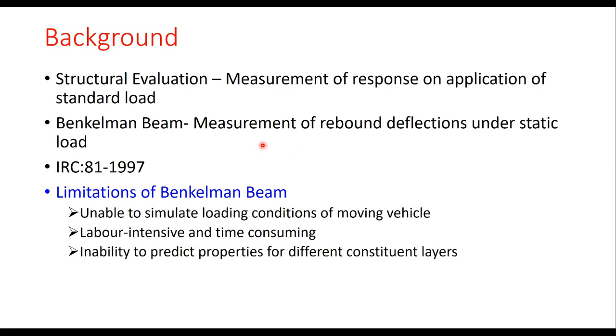For this, you might be knowing that Benkelman beam deflection studies have been carried out for a long time in India for measuring the rebound deflection under static load. This code was last published in 1997, based on research work done during 1984 to 1990. But the major limitation of this method is that it is unable to simulate loading conditions of a moving vehicle.